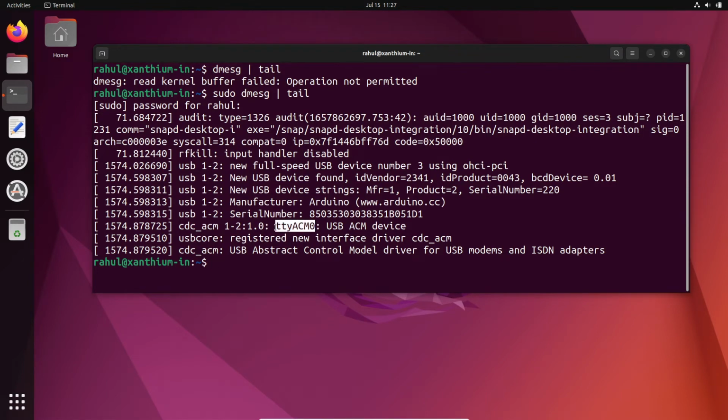So when we are using serial port programming, we have to give the port number as /dev/ttyACM0. By the way, if you are using a different type of USB device, it will be different. For example, if you are using FT232 devices, it will show as ttyUSB0. So now we have the port number, then we can use it to access our device.